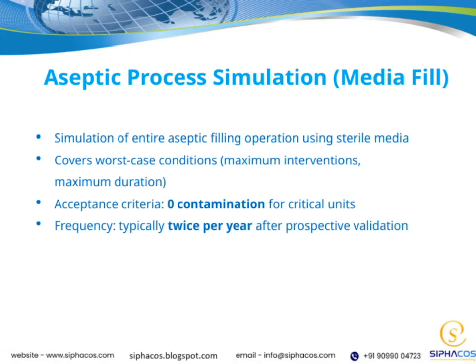Now, let's talk about the simulation of the entire aseptic filling operation using sterile media. This process is designed to mimic real-world conditions as closely as possible. We focus on worst-case scenarios, which means testing under maximum interventions and the longest durations to ensure robustness. The key acceptance criterion here is zero contamination for critical units, as any contamination could compromise product safety. These media fills are typically conducted twice a year, following prospective validation, to verify that our processes remain under control.